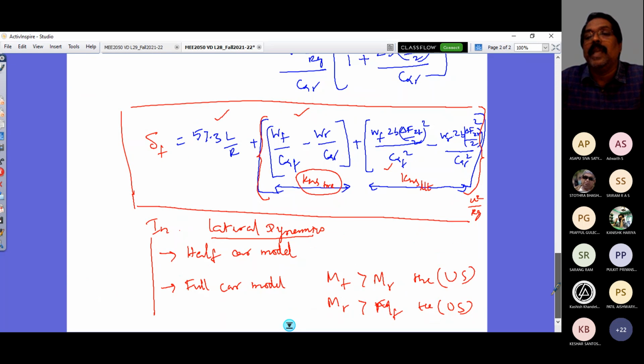So if we are taking here the value of change in normal load in a single wheel, then it should not be divided by 2. But in our derivation right from the beginning, this delta F is at F is the change in 2 wheels. Divided by 2 is what it will come per wheel. And that is to be carefully understood. And of course, this WF appearing here is the 2 wheels normal load, right? So with that clarity, we have just finished in the last class